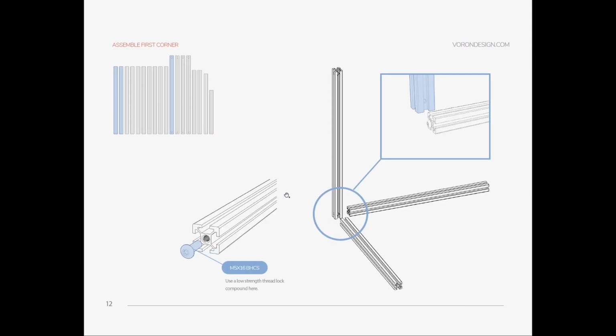And while you are doing the blind joint, this is I think the more convenient one. You can also use corner cubes, etc. But I would recommend you go with the blind joint. It's more rigid, I guess, is what I'm thinking. So for that, if these are pre-tapped and pre-drilled, it's slightly easier for you.